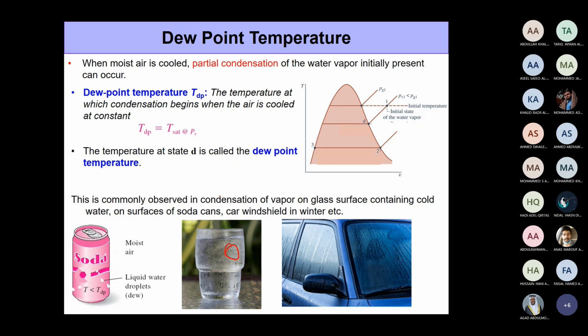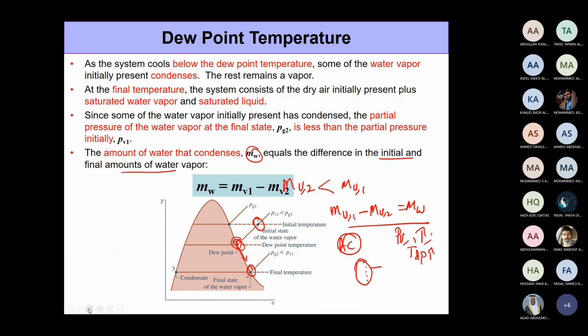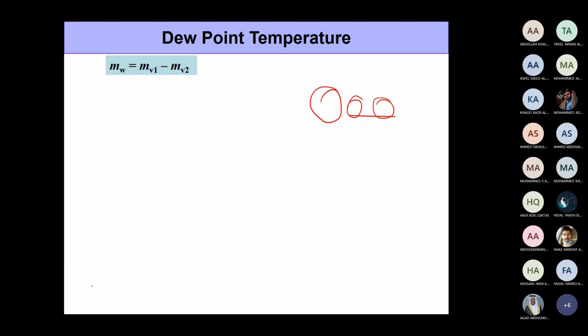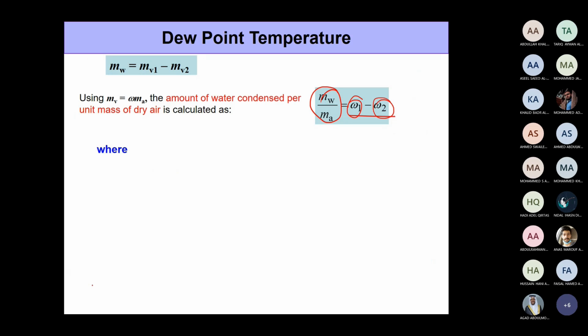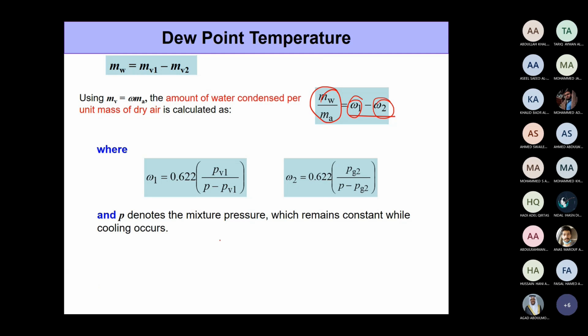On the other hand, you can also have dew. Typically, dew is observed later in the night. At night, sometimes the temperature goes below the dew point temperature, right? For the amount of water vapor that we have in the air, sometimes on humid days the dew point temperature could be as high as 25, but during the evening the dry bulb temperature can become maybe 20 degrees Celsius. So at this point, all the water vapor in the air, or some part of it, starts to condense, and this shows up on any surface you can see.